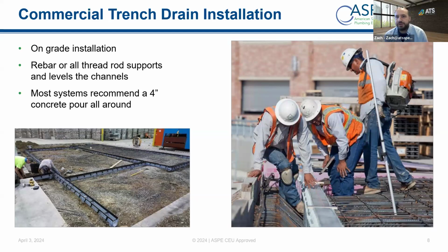So I think really, one of the questions that I get asked all the time is how much concrete do they need either on the side or underneath? So underneath, probably 4 inches is a good rule. And then you'll need whatever space you need to get that concrete underneath and make sure it's fully supported underneath the channel.